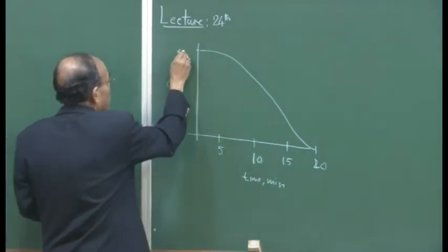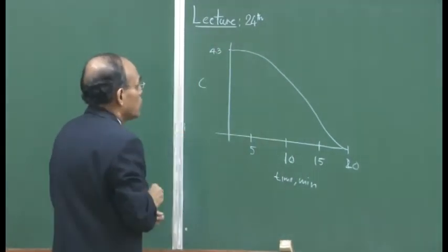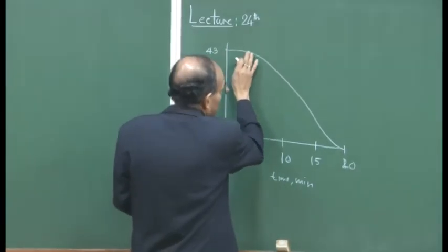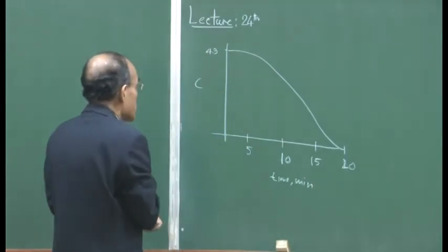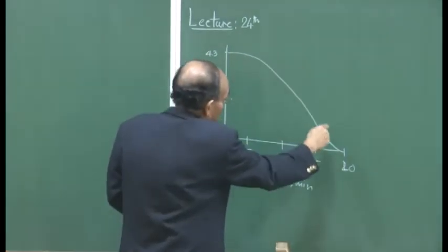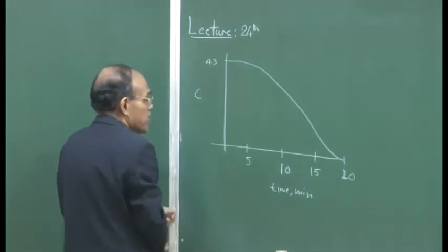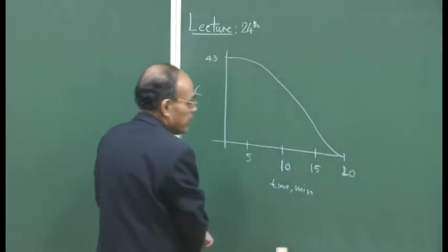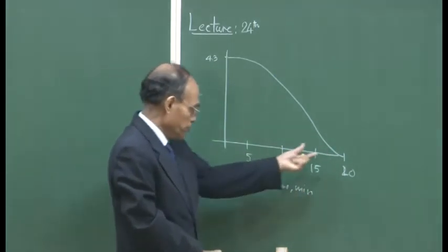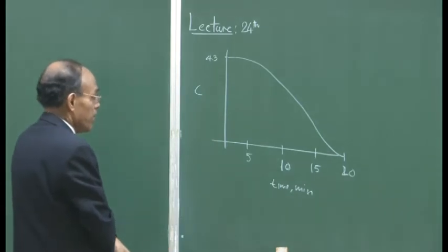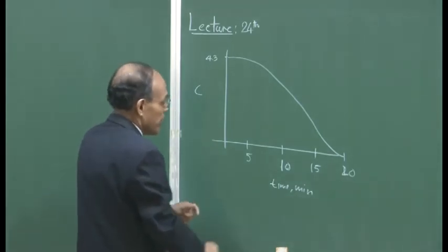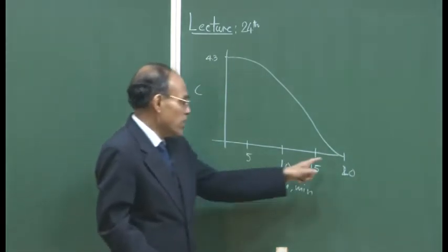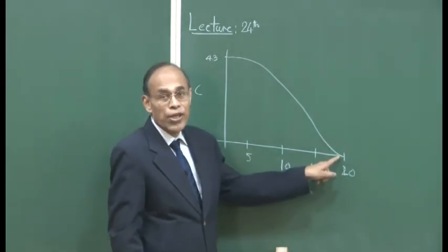So initially you have a rate increasing, and then the rate becomes steady. This is the part where we have a straight line graph. So, dC/dt is negative, but it is constant, and then in the final tail end we have dC/dt, or rate of decarburization, progressively decreasing with time. As I have indicated, this need not be 0 as I have labeled it.